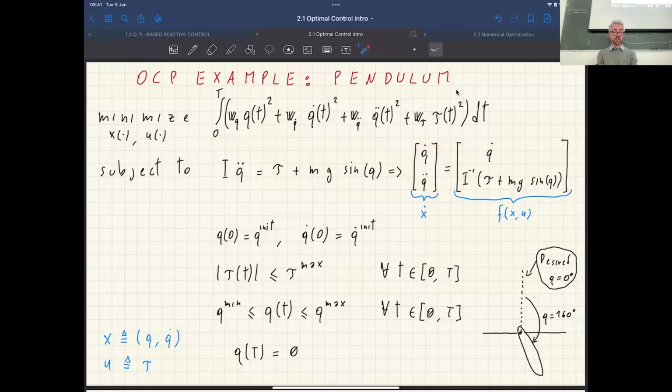And anytime we are not at 0, we are paying some extra costs, because we are adding this Q square to the cost. So having Q there is basically like asking the solver, not only I want you to reach 0, but I want you to reach 0 as fast as possible. Okay, and the higher this weight, the more important that request is going to be with respect to the other requests. Because here we are asking the solver to do several things at the same time, and these several things are incompatible with each other.